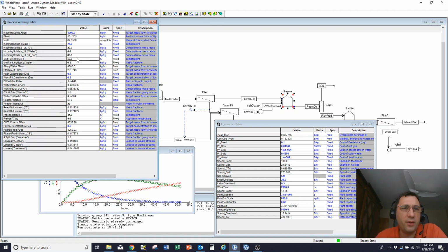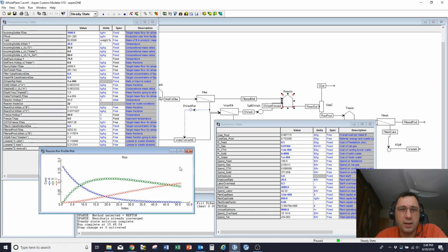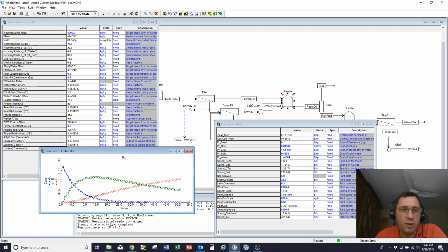So let's pretend that the maximum I can bring this material to is 75C. So let's raise the temperature to 75C and rerun the simulation. You see the curves have moved quicker, moved towards the left. The peaks got slightly higher. I've now also got my maximum at closer to 14.